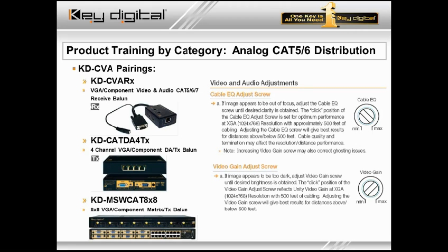You may see some skewing of your image. Have no fear, the cable equalization screw can solve those problems, and really it's just a part of every install with the CBA-RX balun. Again, it's just going to take you a minute or two with a flathead screwdriver.